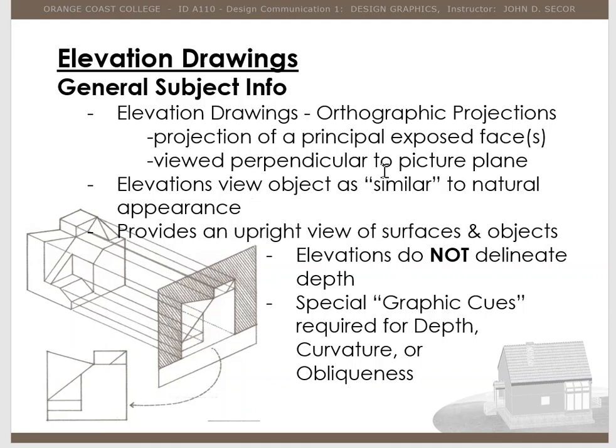So this view is perpendicular to the picture plane. So when we have a plan view that is parallel, and as we project the lines outward, they're perpendicular, they create a different viewpoint. So this provides an upright view of the surface. Remember, we're like tilting a wall up, and that's what an elevation is.